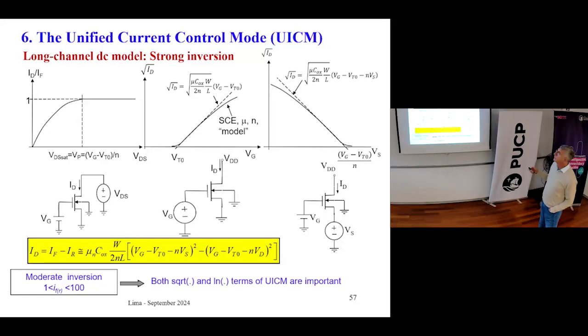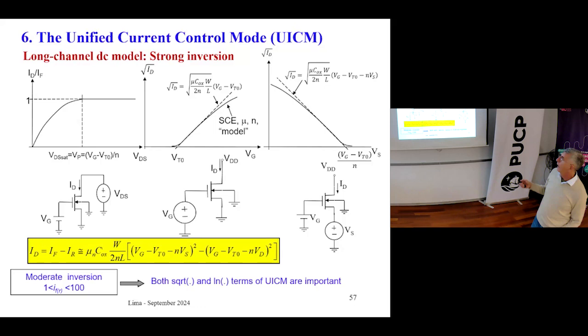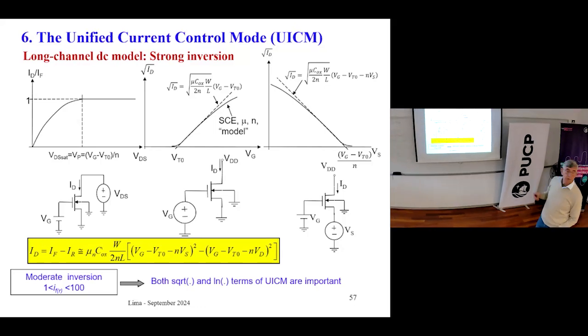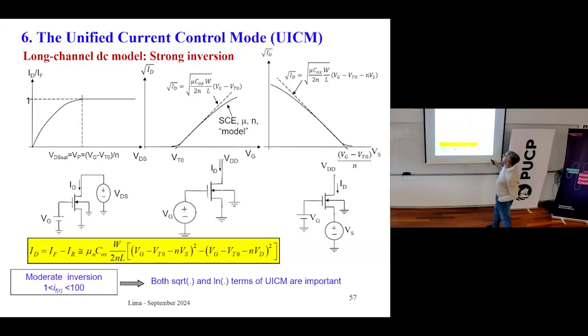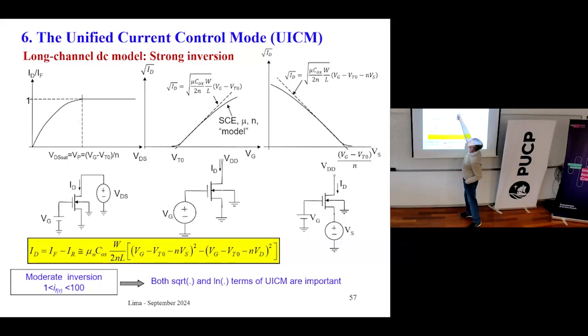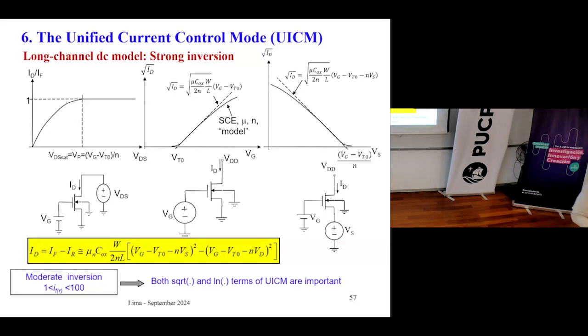And you also have some distortion of this straight line for high voltage because the mobility is a function of the gate voltage, and mobility decreases with the gate voltage. So the factor n is also a function of VG. So you have a distortion here. I'm explaining this because in the past, the community used to determine the VT0 by extrapolating this curve of the transistor. But this is not simple because you can extrapolate this region here. Oh, this is complicated because you have some distortion. Or you could extrapolate the curve for higher gate voltage. Oh, but this would give a different VT0. So this is not correct for the extraction of the threshold voltage. We need some other methods that give us a better result for the threshold voltage.